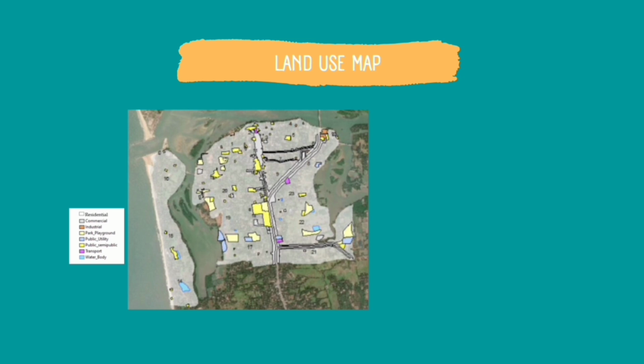Now this is the area for which we need to design the water distribution system. But as we have already seen, there is about a 10,000 increase in population till the year 2046. Again, this is not going to get distributed uniformly in this area. So there must be a methodology by which we can tell which areas will get more population and which will get lesser.